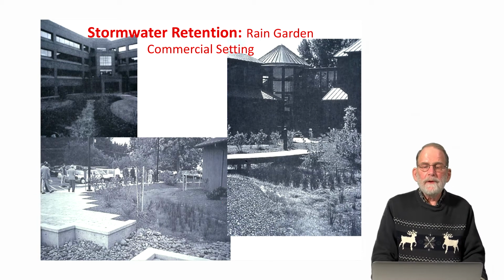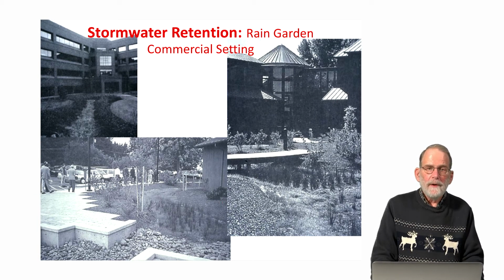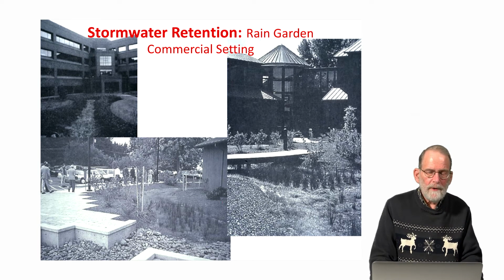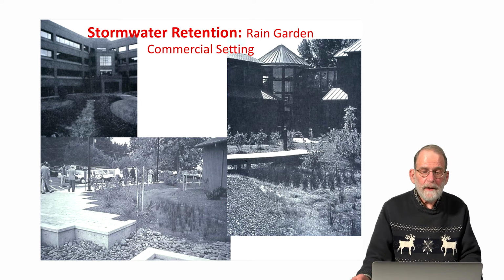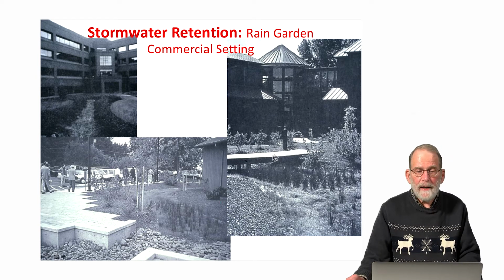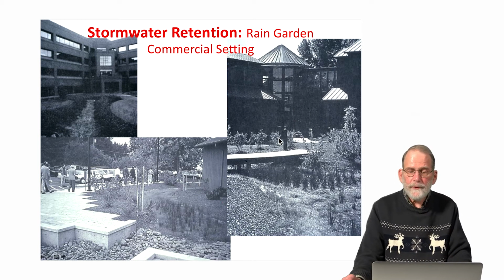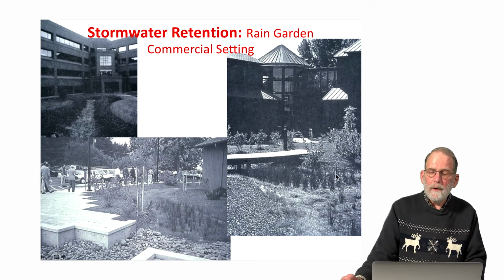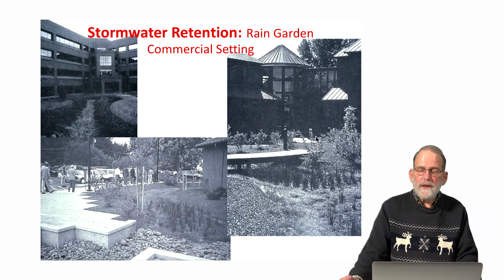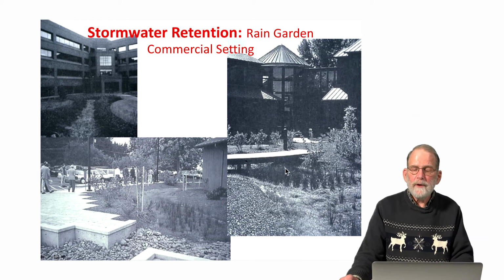So in this part, I'd like to talk about the concept of rain garden, because the concept of rain garden really puts together some of the different strategies for retention of water on site. And in these slides, we can see, especially in the upper right, water coming off of the rooftop of the garden, water coming off of paving surfaces is put into a bioswale. The bioswale runs throughout the landscape, so water is sheeting across the landscape, flowing into the bioswale.